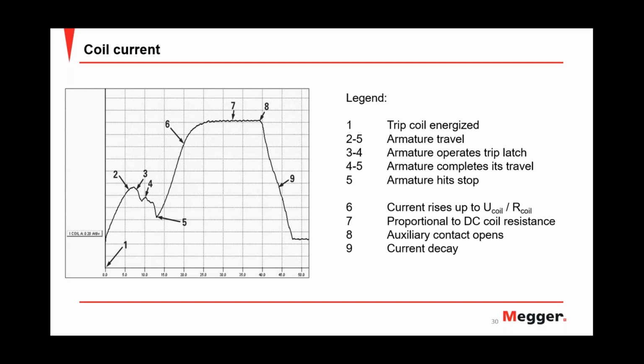If the coil were to reach its maximum current before the armature and latch start to move, the breaker would not be tripped. It is important to note the relationship between the two current peaks varies with some parameters, particularly with temperature, and again that applies to the lowest tripping voltage. Measuring the coil currents on a routine basis will detect potential mechanical and electrical problems in actuating coils well in advance of their emergence as actual faults.